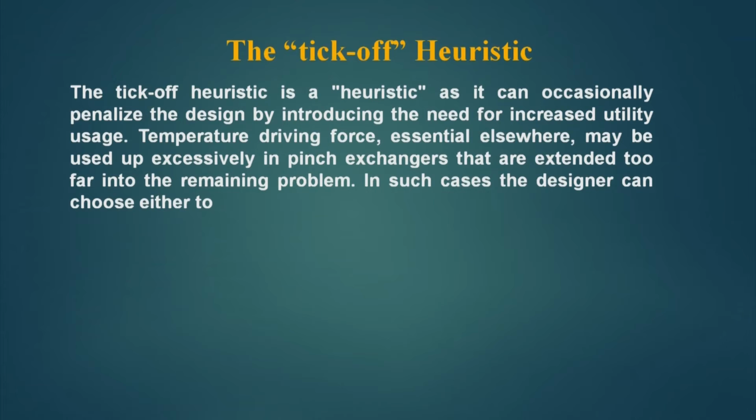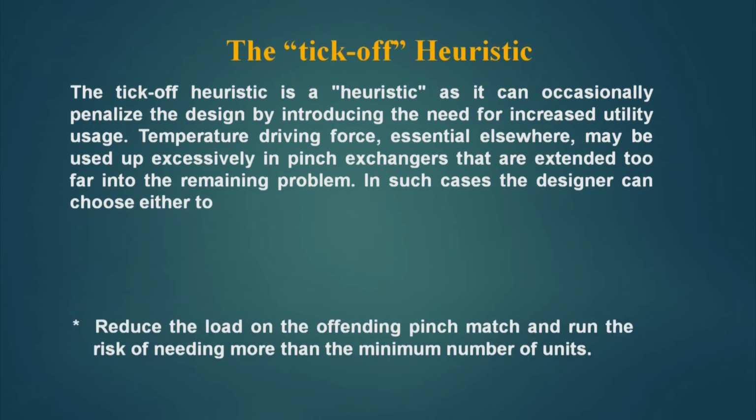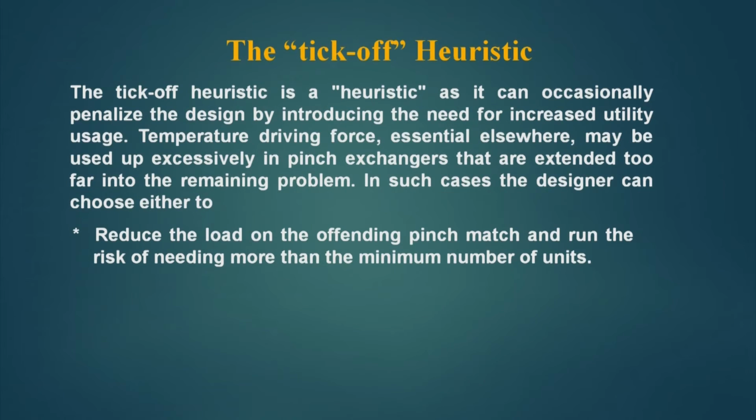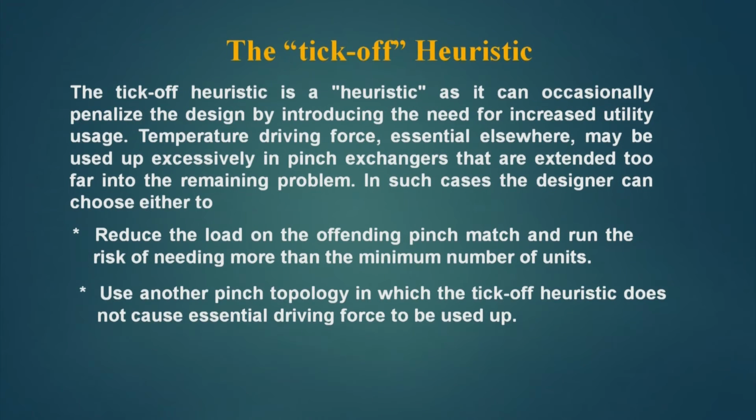Temperature driving force, essential elsewhere, may be used up excessively in pinch exchangers that are extended too far into the remaining problem. In such a case, the designer can choose to either reduce the load on the offending pinch match and run the risk of needing more than the minimum number of units, or use another pinch topology in which the teacup heuristic does not cause essential driving force to be used up.